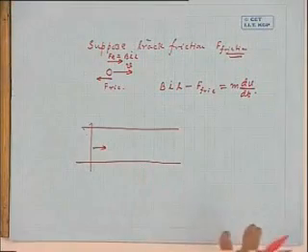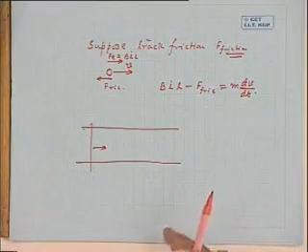It will accelerate, of course, only if the BIL developed at t equal to 0 plus is more than F friction. It starts moving, so the electromagnetic force acting on the conductor is greater than the frictional force. That's why it is accelerating. It accelerates with time. But with time, what happens to this electromagnetic force acting from left to right?